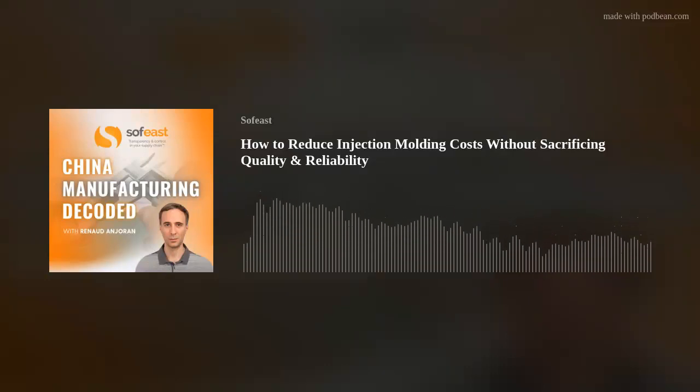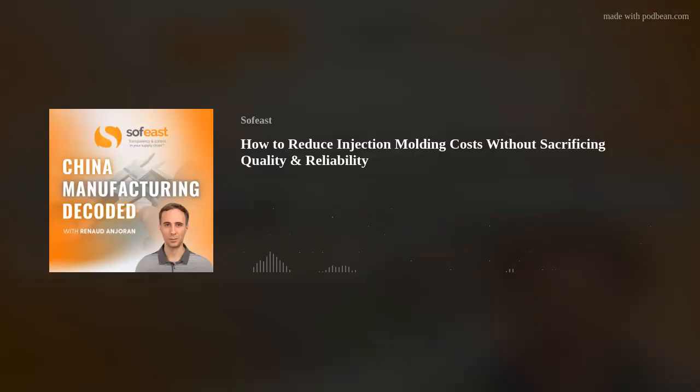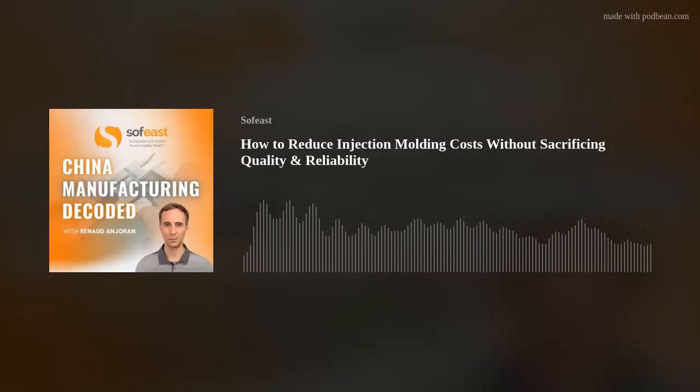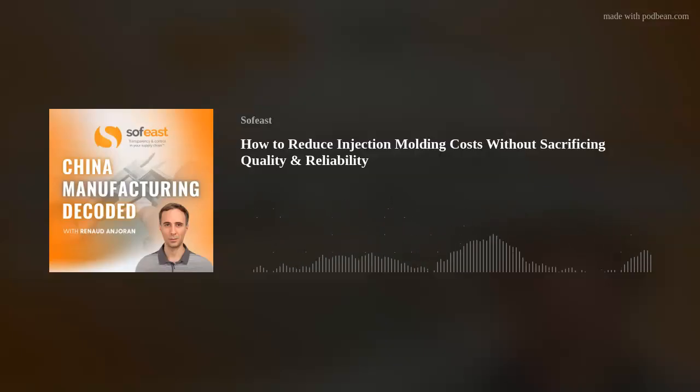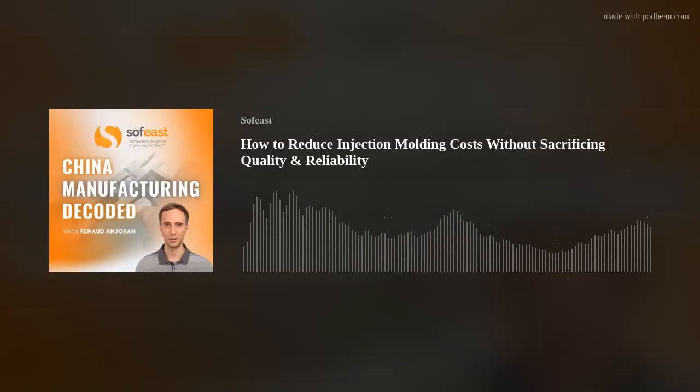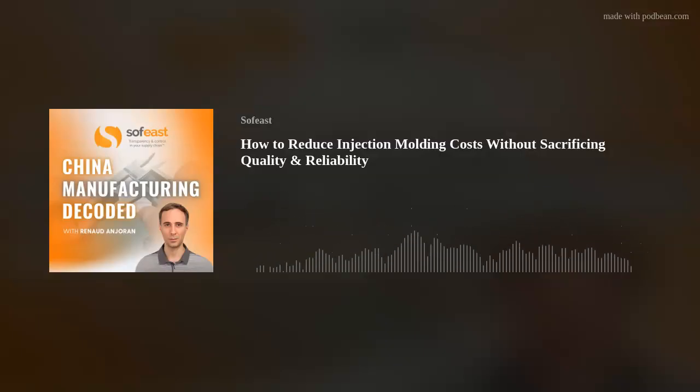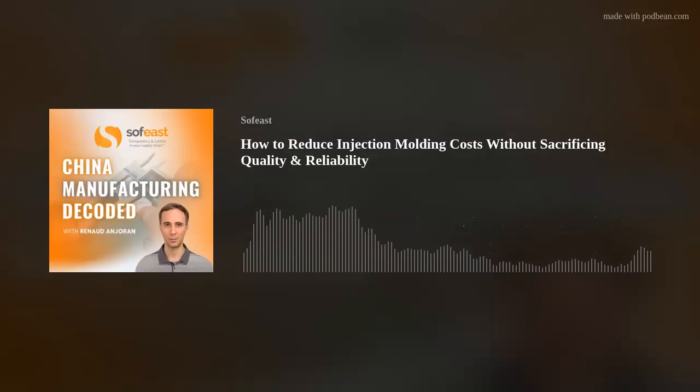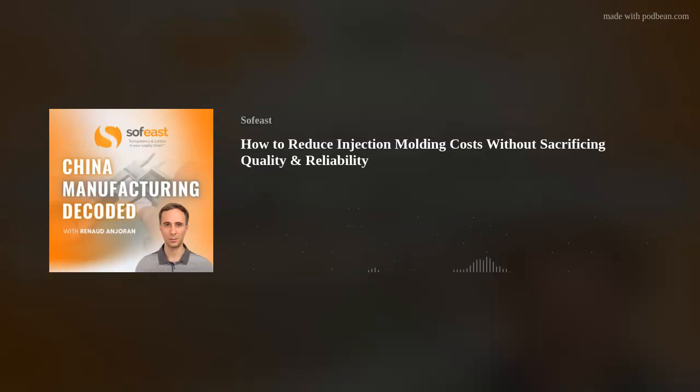That's where a weld line or a knit line can form if things go wrong and it's frozen too quickly. You're going to have a line there. In other words, it's going to be a weak point in the part. You can actually eliminate that simply by the gate size and position. So again, it's talking to your tool maker to make sure that all of these critical areas are looked at from a best practice point of view, from an optimization point of view.